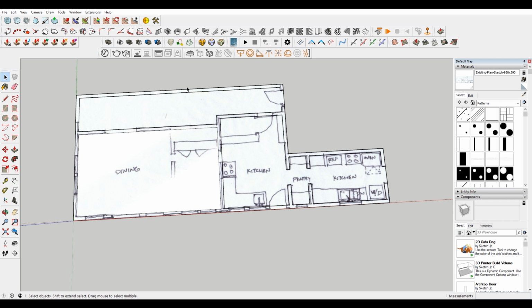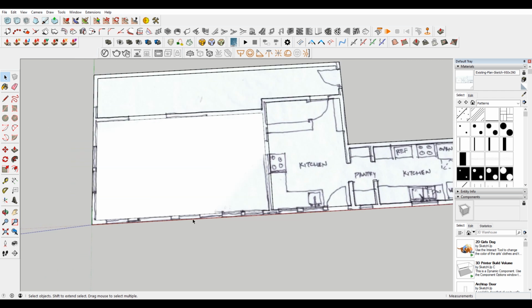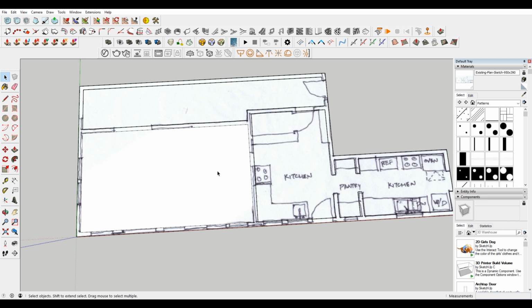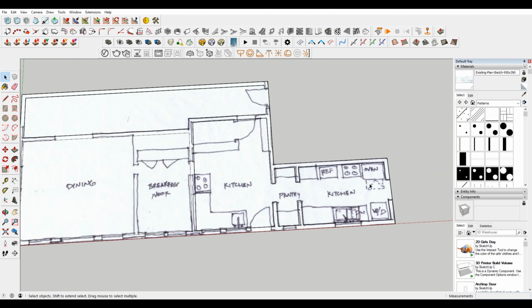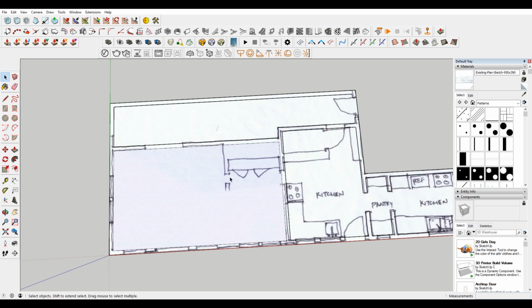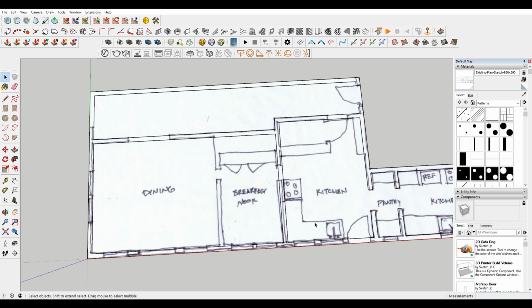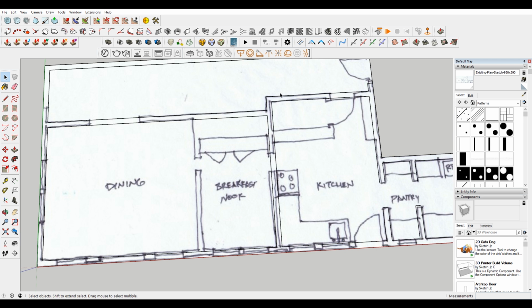Or maybe even here, where you have a lot of openings, it may not be a structural wall because there are so many openings. Here has a ton of openings, so I'd think that actually these two walls are structural, but I could also be wrong. But having that kind of mindset when you're going through this is really important, that this wall continues all the way through, that they're not going to jog it.